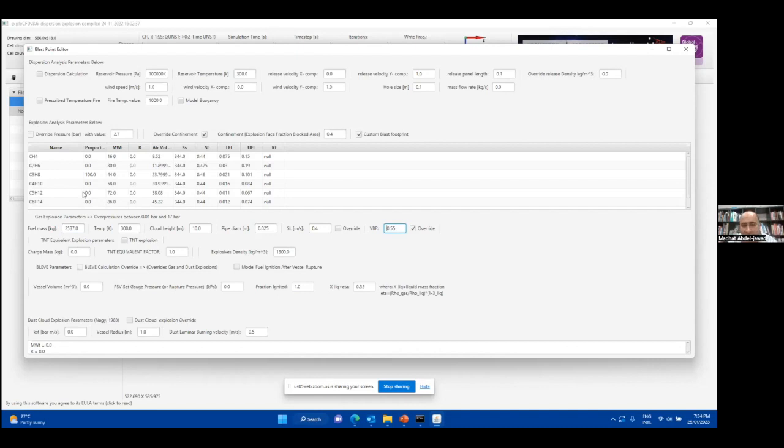Typically, it's very difficult to do explosions with benzene, and typically what people do in industries is run propane instead. They're fairly close in terms of energetic release, especially if benzene has to be a gas cloud, so it's got to evaporate first. So if you take that part out, the ignition of a benzene gas cloud and a propane gas cloud, they're ballpark similar, let's say.